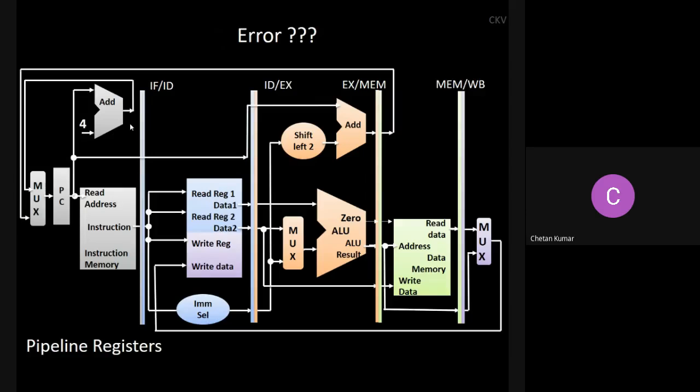Something with the muxes, multiple inputs to a register. A register can have multiple inputs. That's not a problem. And remember, each register is not of the same size. That is one very important point I'm telling you right now. Each register size is different. We are just talking about the data path. Can you take a guess how much? Again, I'm not including control signals. Control signals will require another set of registers, another set of storage elements, which I'll explain.